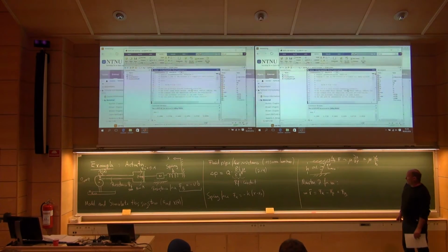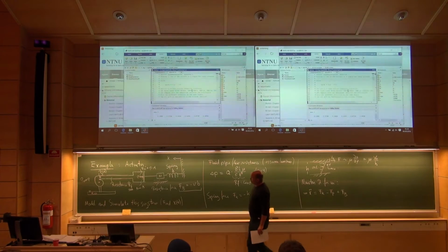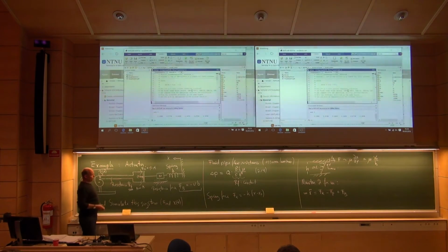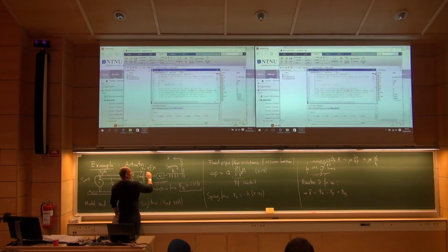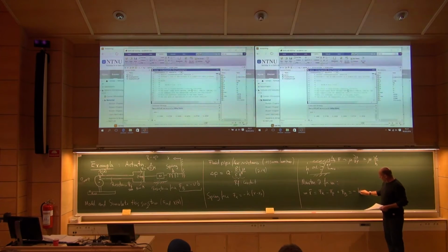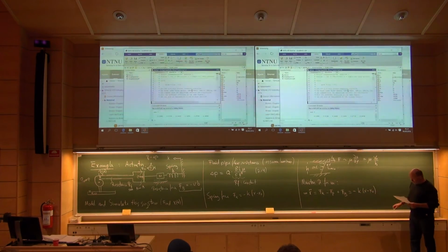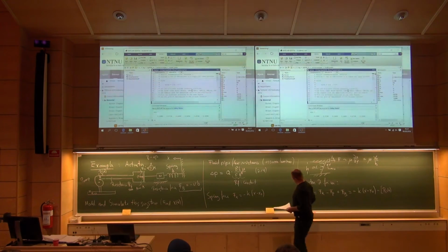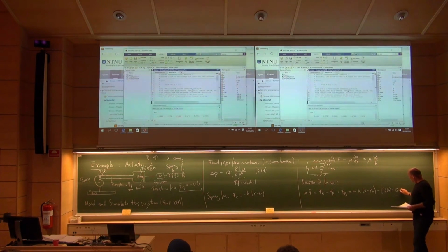And then finally, what else do we need? Nothing more. I'm missing the resistance here, the delta P pressure drop in this pipe, but you will enter here. Let's do that. It will be the source pressure minus this delta P. So let's see if this one is correct. X minus X0 spring force, and then we have the pressure. Well, that should be delta P, which then again was Q times R.